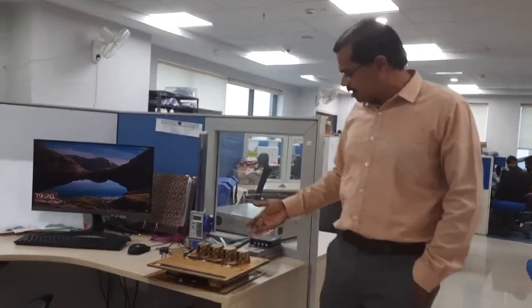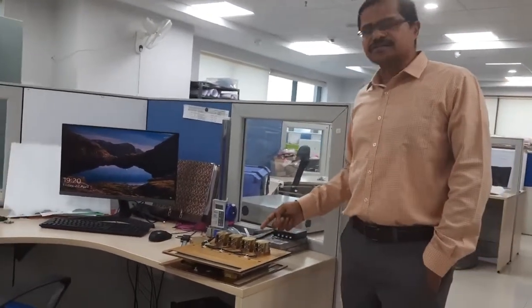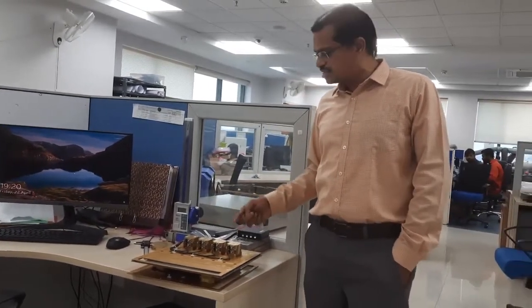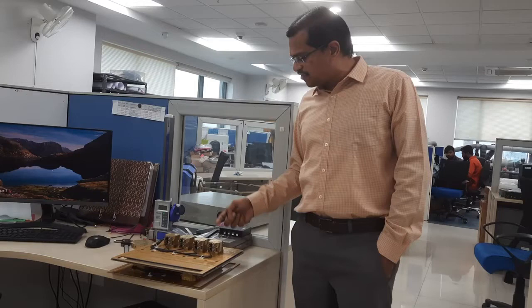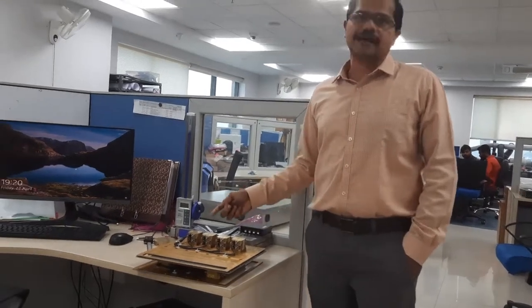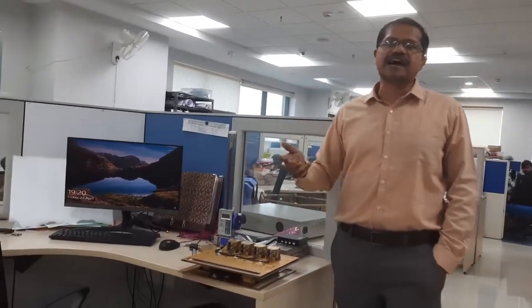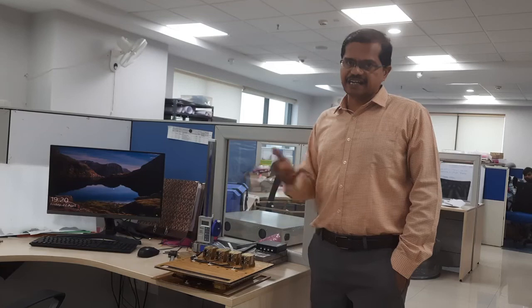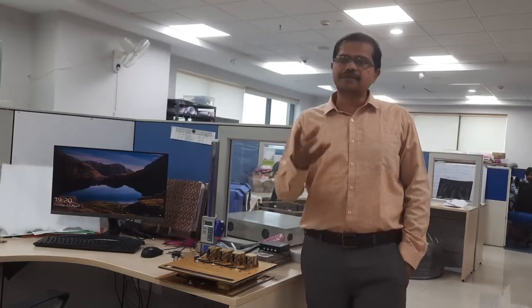So here you can have a look. These are amplifiers which are capable of covering 100 megahertz up to 6 gigahertz. These are low noise amplifiers; people who studied RF and communications know the importance of noise figure. We build these right from scratch. We buy the PCB material, high frequency PCB material like RT Duroid and Rogers, then we design the PCB layout.